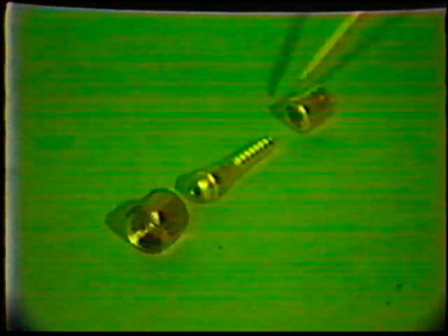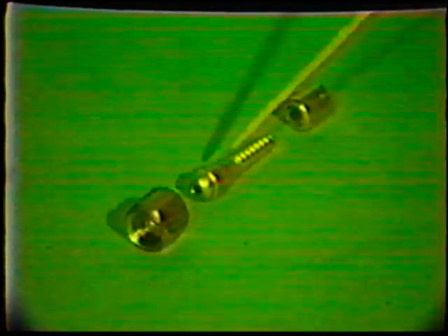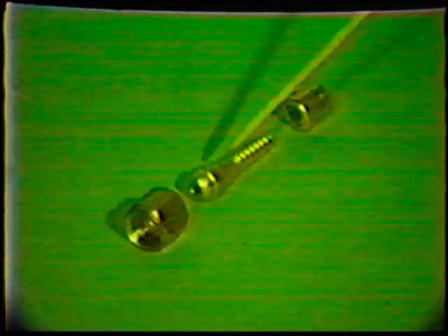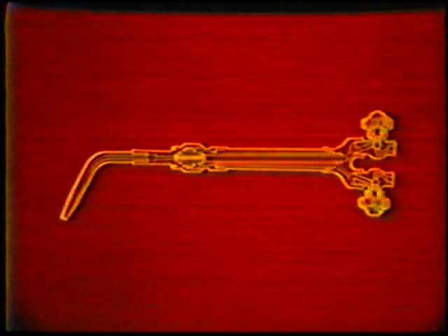The hose fittings or connections consist of three parts: a hose ferrule or clamp, which locks the hose onto the nipple, a nipple with a seating surface to match with the internal seat on the torch and regulator, and a swivel nut to tighten the connections. In assembly, each connection must be gas tight. The torches used with oxyacetylene can differ with each application. However, a change in tip and mixing chamber is all that is required.